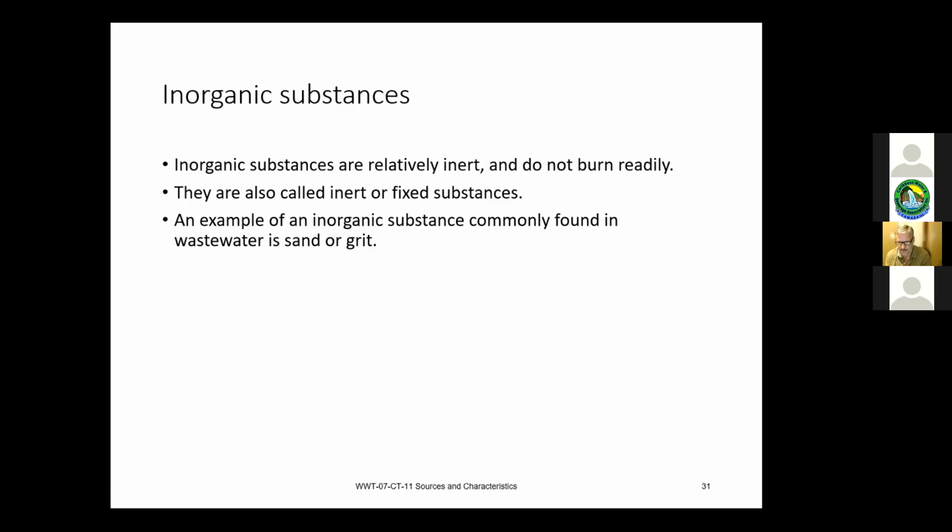These organisms, biomass, bacteria, whichever term you're comfortable with, all want to survive. So they need air that we provide and the food from the wastewater. Sand and gravel, for example, inorganics, is not something they're going to live on. It needs to be removed. From a process point of view, if it's removed at the front of the plant, that's the best way to go. If it winds up in your plant in large quantities, it will affect valves and pumps. It could build up in corners of tanks and affect the process as well.